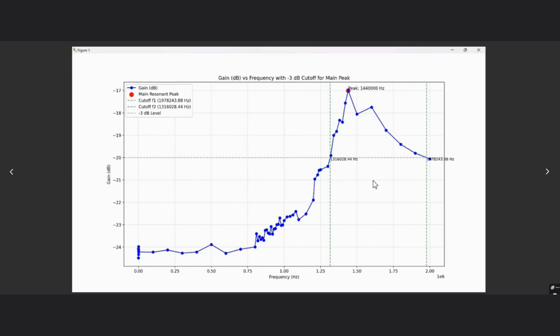In the procedure for our experiment, the LED and the photodiode were positioned facing each other to maximize light transmission, as shown in the video. We varied the frequency of the input signal while maintaining a constant modulation amplitude. At each frequency, we recorded the input and output voltages using the oscilloscope. We made two graphs: the first is the magnitude response and the other is the phase difference.